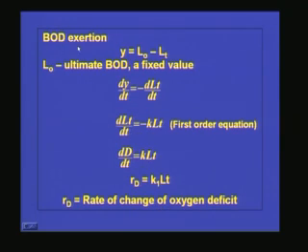BOD exertion we have seen in detail when we were discussing water and wastewater characteristics. BOD exerted is nothing but the difference between the ultimate BOD, which is the initial organic matter concentration present, and the organic matter concentration present at time t. If you take the difference, that is the BOD exertion.